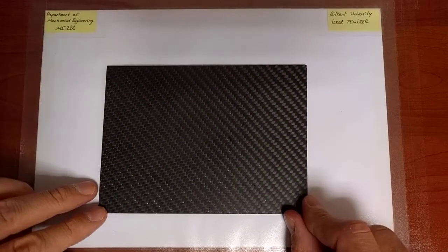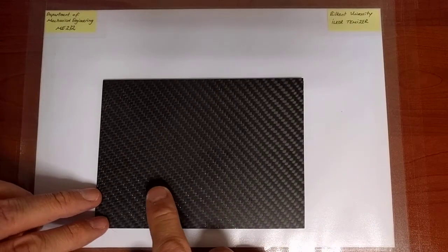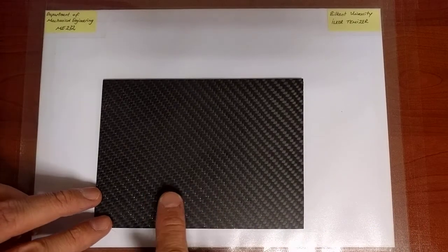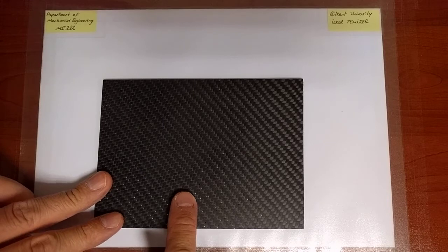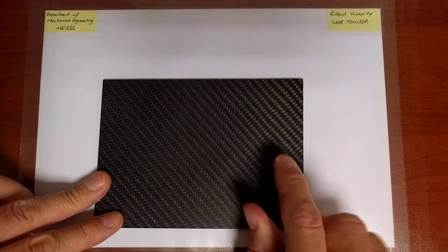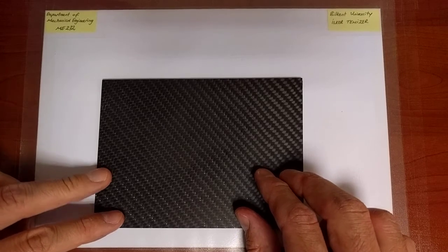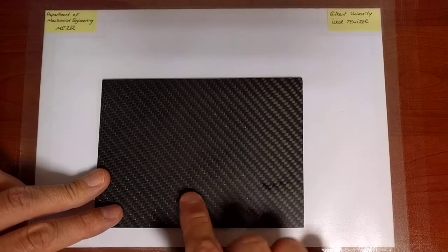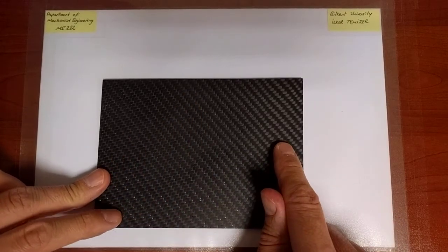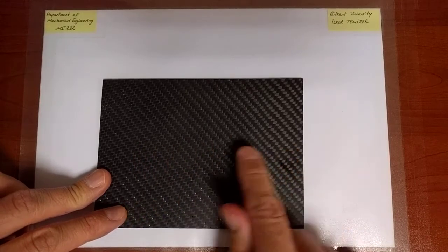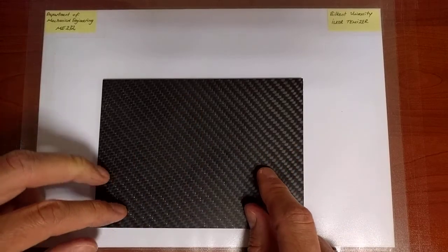But now we've talked about composite materials that are associated with fibers. And here is a carbon fiber composite plate. The fibers are sort of running along that and that direction. So this is very close to being the orthotropic 2D plate that I provided, except that now we have fibers running along two directions. So the Young's modulus along both directions are very, very high.